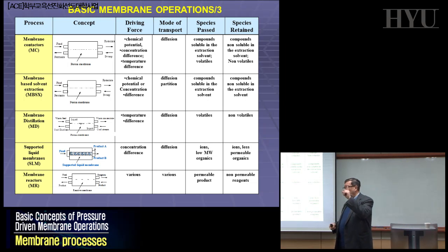technology, particularly in one field, which is the MBR. We will discuss about MBR, I've mentioned already, which are the membrane system combined with traditional biological systems people are using for the treatment of wastewater, municipal water. And this one, where one type big biological pond, etc., where everything is happening. Now this is becoming a membrane system, much more compact, very low footprint, much more effective because it is a reactor. So you have to know how to handle it and it can be handled.